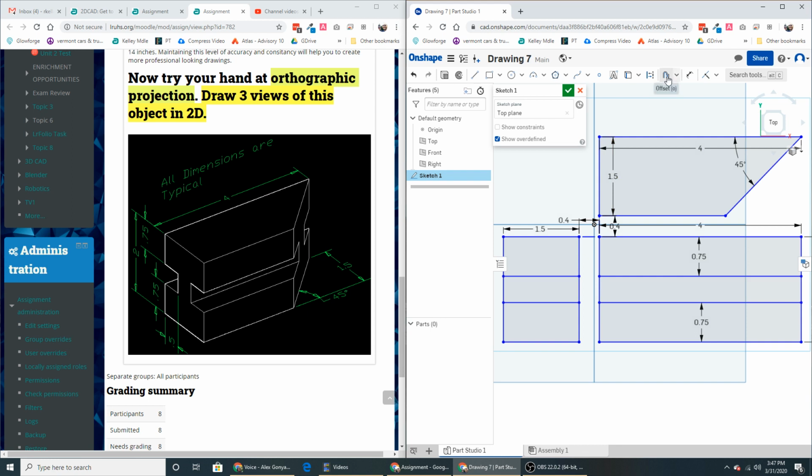So we might as well keep going with the offset. Offset here, this way, 0.5, enter, and here, and this. You know, I did that again, didn't I? Escape, let's undo. All right, instead of grabbing this edge, because it's a full rectangle, I'll grab this line, and we'll just come this way with it.